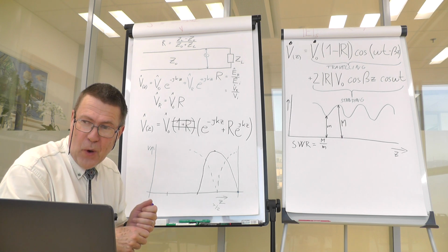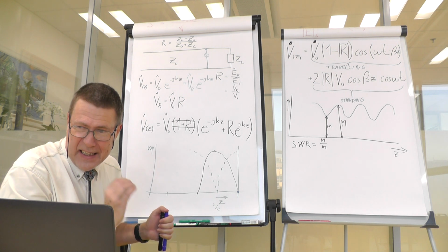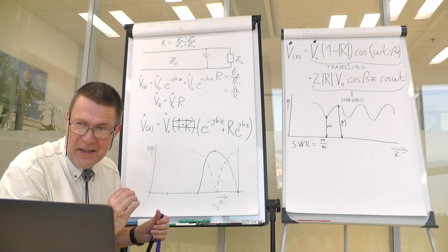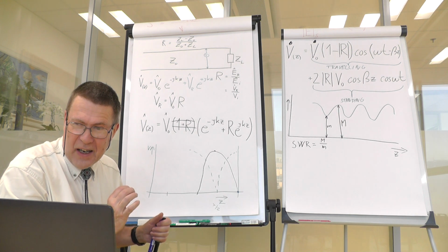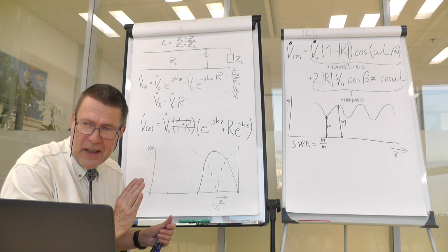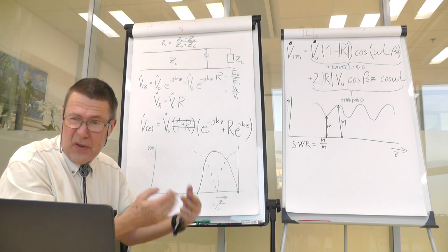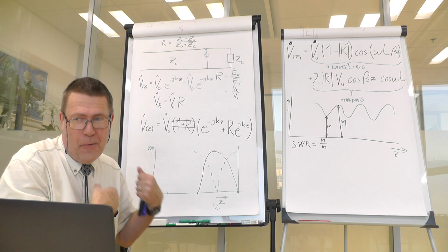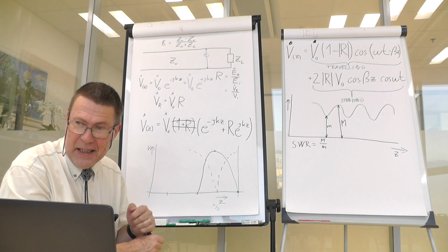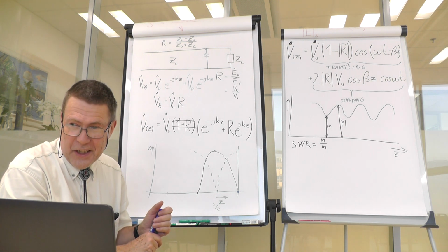For example, if you have a coaxial cable and you just slightly increase the maximum power that you can transmit, then there would be a discharge. For slight increases, it would only increase the losses, because the excess power would turn into heat. But if you have really exceeded the maximum power handling capability, this discharge would generate so much heat that it would destroy the cable.